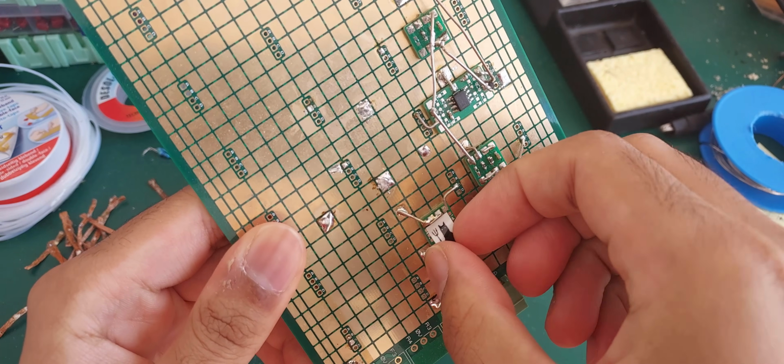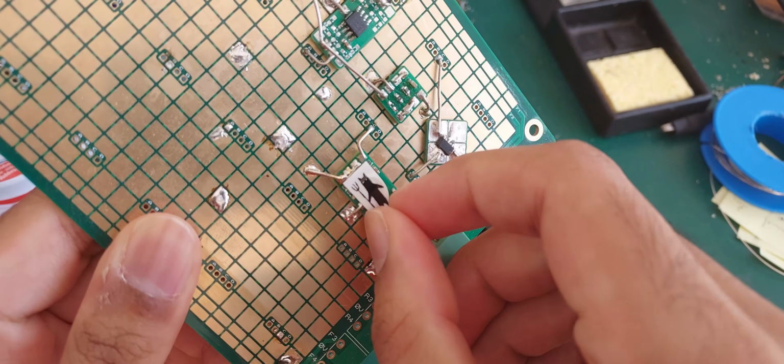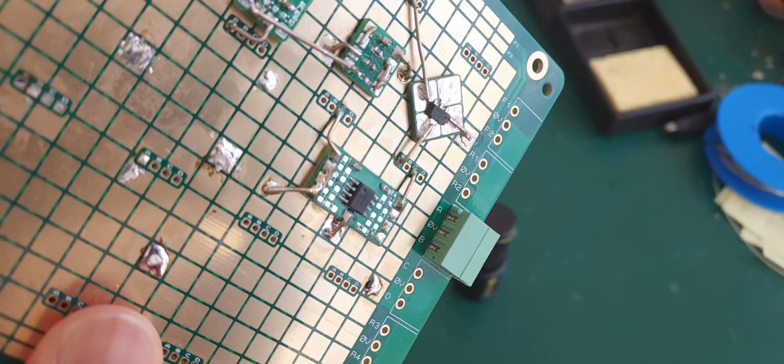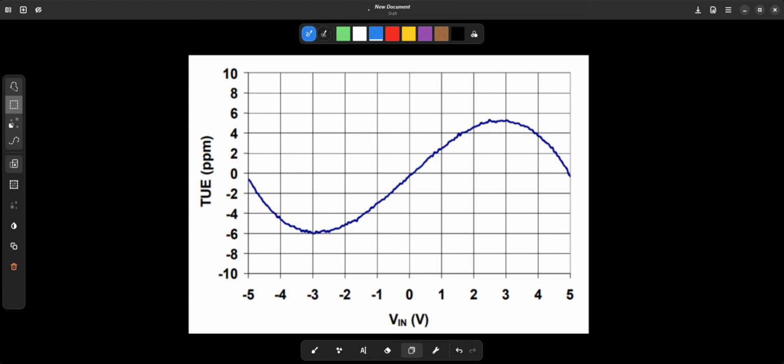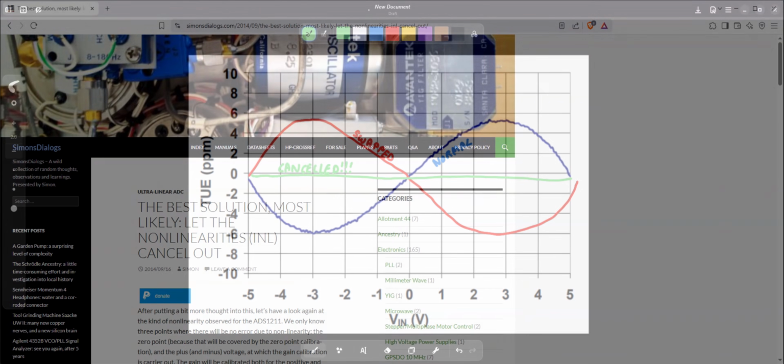I just so happened to have the right part on hand, the MCP3551, which I had to abandon mid-experiment because of the temperamental SPI interface. The ADC's smooth cubic INL is not enough for a sub-ppm calibration. My initial idea to cancel out the INL was to do two measurements, one with the input swapped and one without, with the results of each measurement cancelling out the errors.